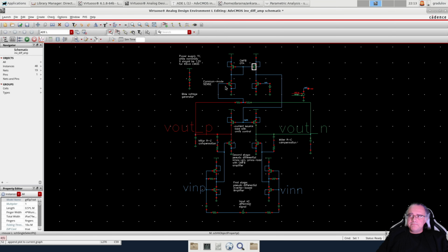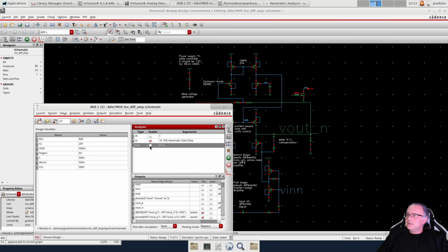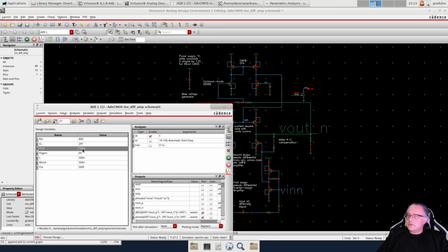This will reduce its gain, but I don't have very high requirements for the gain of the amplifier in the common mode feedback. If the gain is not high enough, there will be a slight offset between the real common mode and the common mode set, which can be compensated by setting our common mode here. So let's see how this operates. Let's first run DC simulation. The important values here are that the common mode at the moment is set to 0.5 volts.